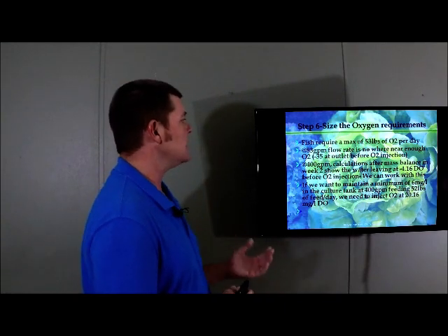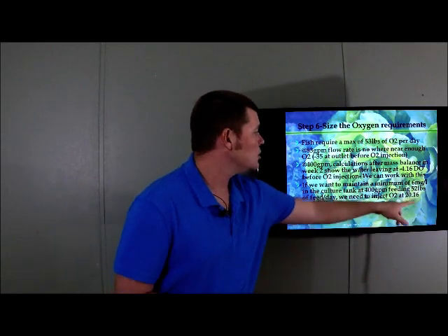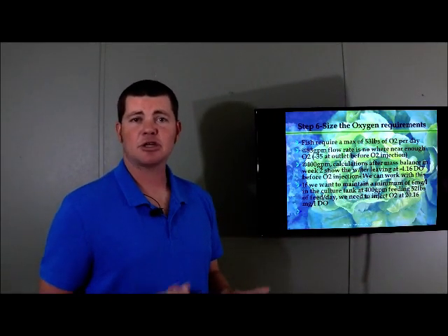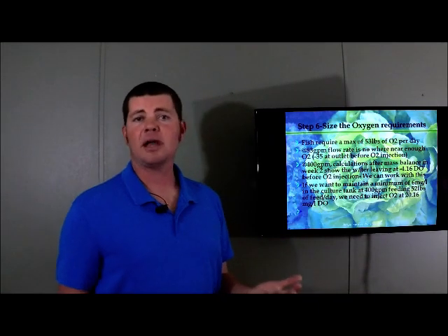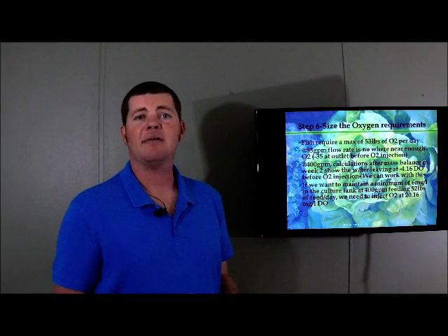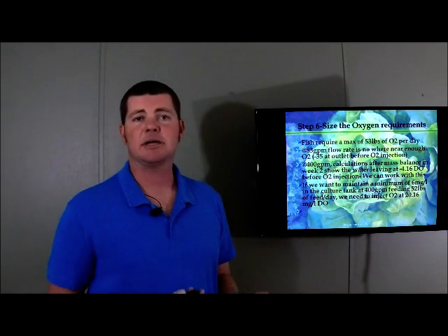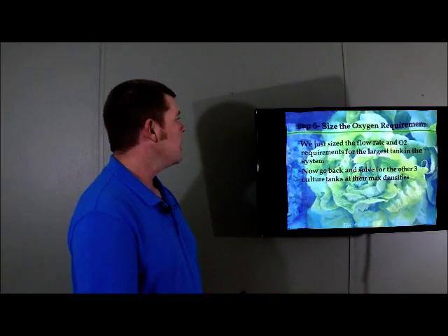Okay, so instead of coming in at 10 and leaving at negative 4, we're coming in at 20 and we're leaving at 6. Does that make sense? We could not achieve that with normal aeration, right? Because we can't get above 8 to 10 milligrams per liter. But with oxygen, we can saturate the water above that. So that's what we're going to design around.